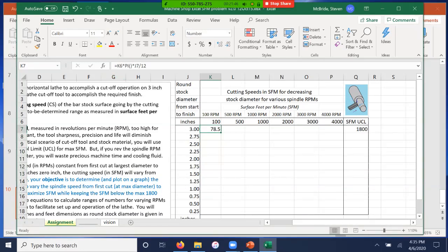So I'm going to look at this. The K6, as I bring that down, I want it to stay on row 6. So what am I going to do to this equation such that I can replicate it, but it's going to stay on row 6? Right, I'm going to put a $ sign in there. So I put a $ sign in, then I can hit enter. Now, when I copy this and pull it down, when I'm down here, it still says 6.